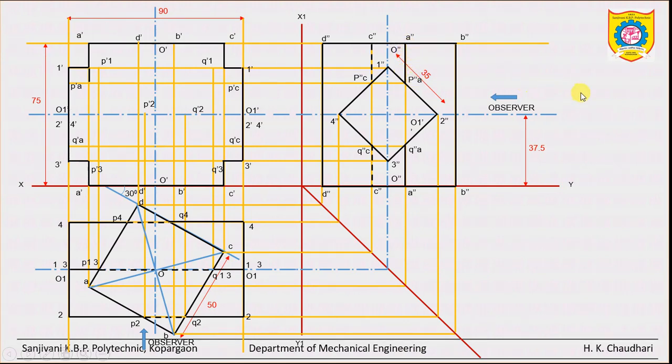So when we observe the intersection from this side, it is in front of this horizontal prism. So up to PA we have made a thick line here. Okay, and from PA to P2 again a thick line. Clear? From the bottom also, up to QA we can make it thick, and from P2 to QA again here, see, 2 to QA we can draw the thick line.